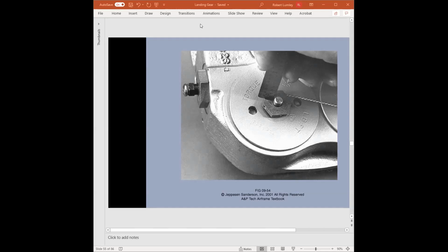As shown here, they're demonstrating the measuring of the adjusting pin, and understand that the adjustment pin, as it gets pulled in, indicates wear. So we're making sure that it sticks out far enough, or beyond its limit. If it gets below a certain distance, this is an indication that the brake linings have worn too much and need to be replaced.